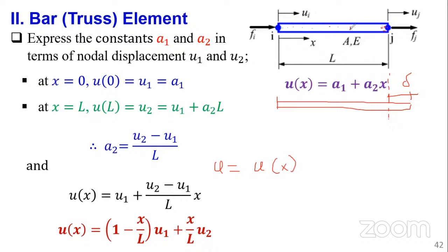So we are saying, when this member is elongated this way, if we had marked a point x here, which was maybe 3/4 L, or 0.75 L, and we are measuring this length, it is not just the elongation of the material from here to here, but a contribution of all the material before this point x, okay?